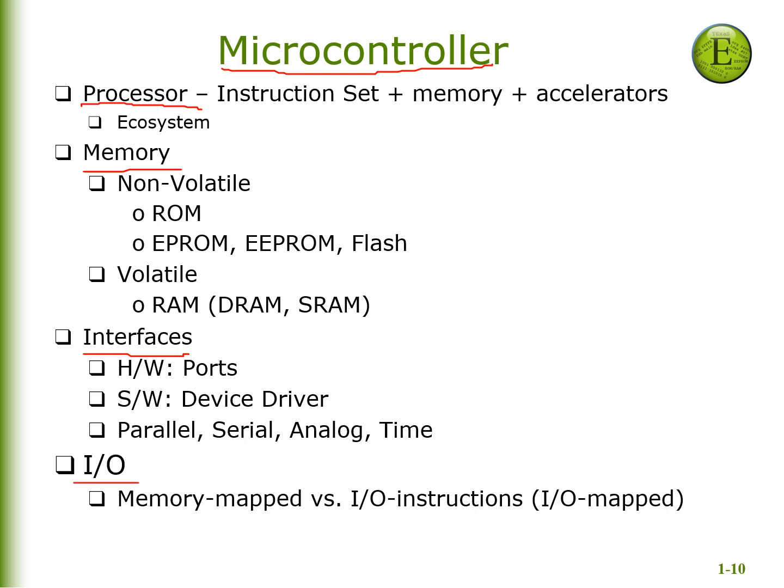So remember, the processor is the basic processing component of the microcontroller, and in order to process the data, it needs some memory from where it can retrieve the data, process, and write back. And the memory can be volatile, such as the random access memory that we find in our computer systems, in which if the power is turned off, the data is lost. Or it can be non-volatile. A famous example is flash memory, which is a type of EEPROM, the electrically erasable programmable read-only memory, that is capable of retaining data even if the power is turned off.